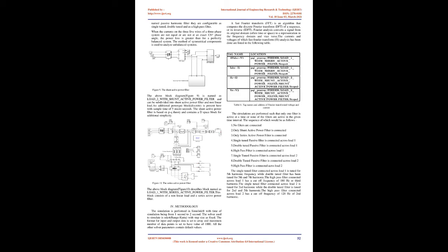3. Methodology and experimentation. For the detailed model of the experimental setup, please visit Model for Harmonic Mitigation. Experimental setup. The power system consists of a solar PV array connected to a three-phase 500 V grid with a fundamental frequency of 60 Hz. The power GUI block is a discrete block with sample time 33 microseconds. The measurement and metering subsystem contains blocks that measure active power, kW, reactive power, kVAR, power factor, total harmonic distortion and maximum power point tracking measurements.